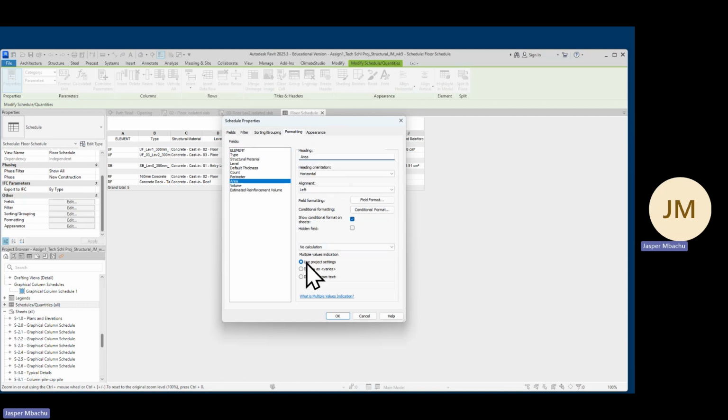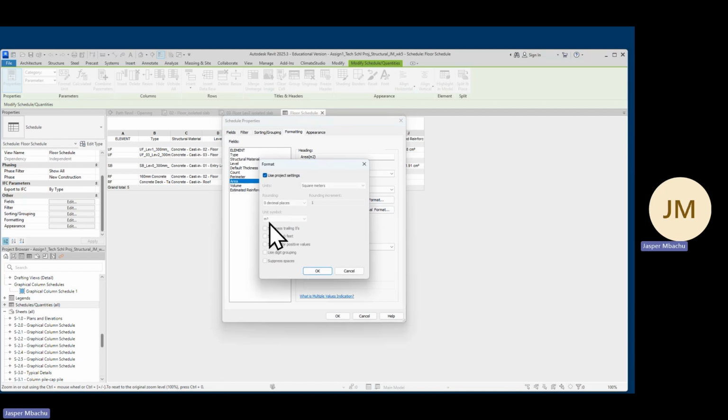And here under the heading, we'll put M2. Bracket opens, M2, bracket closes, for that area to show that after the symbol is removed, what we're seeing there will be meter squared. So we go again to field format. Because the symbol is displaying here, we need to untick this.